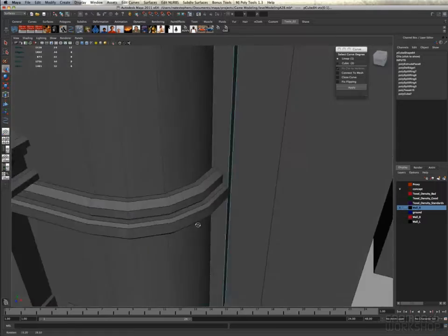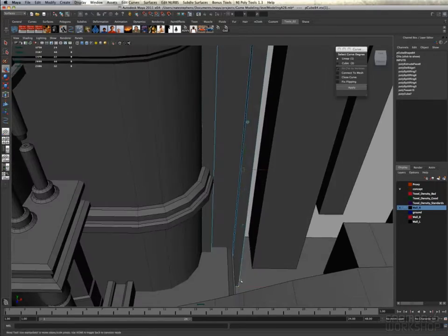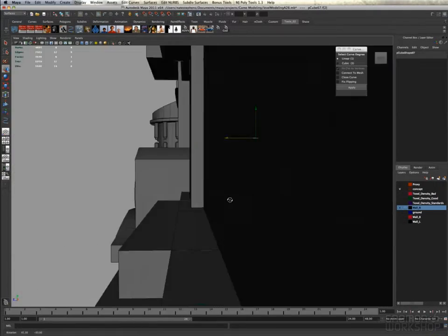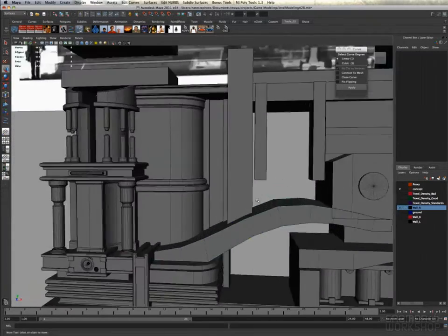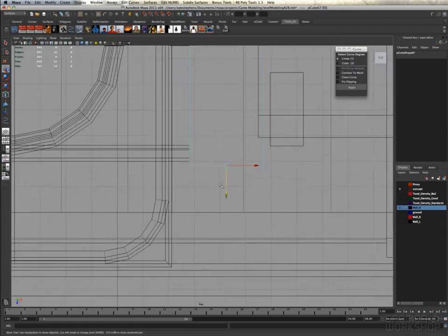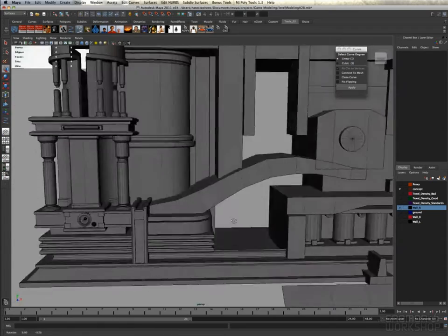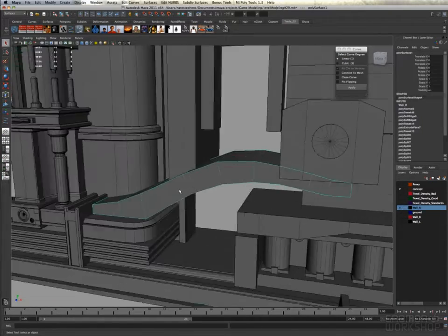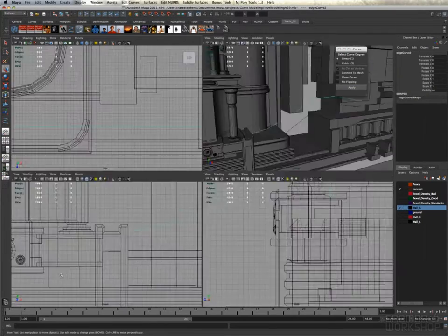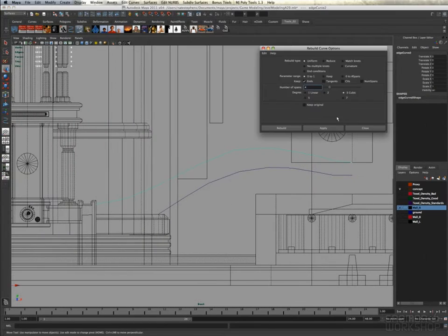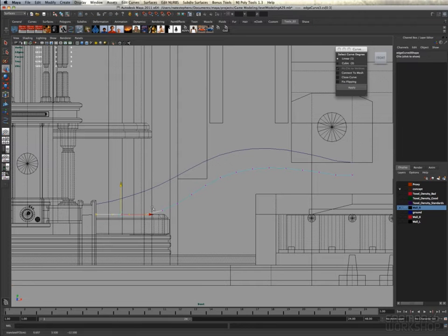So it's a fine line of determining that minimum amount of polygon you need and planning for what you can achieve later with texturing. For example, going back to that vertical box, if I was to go in and start modeling out all the dials and do it all through polygons, my scene would just be too expensive, where I could get the exact same look through a nice normal map and a good diffuse texture.